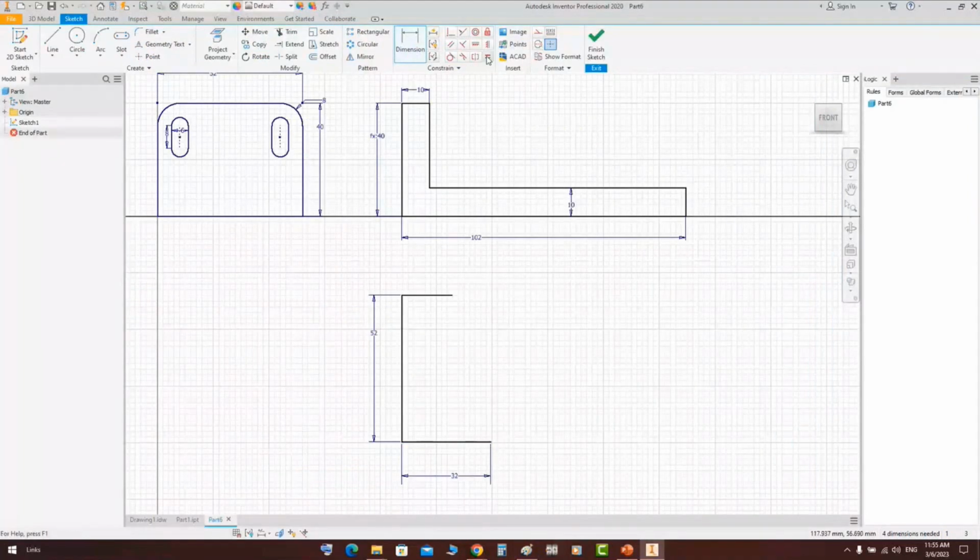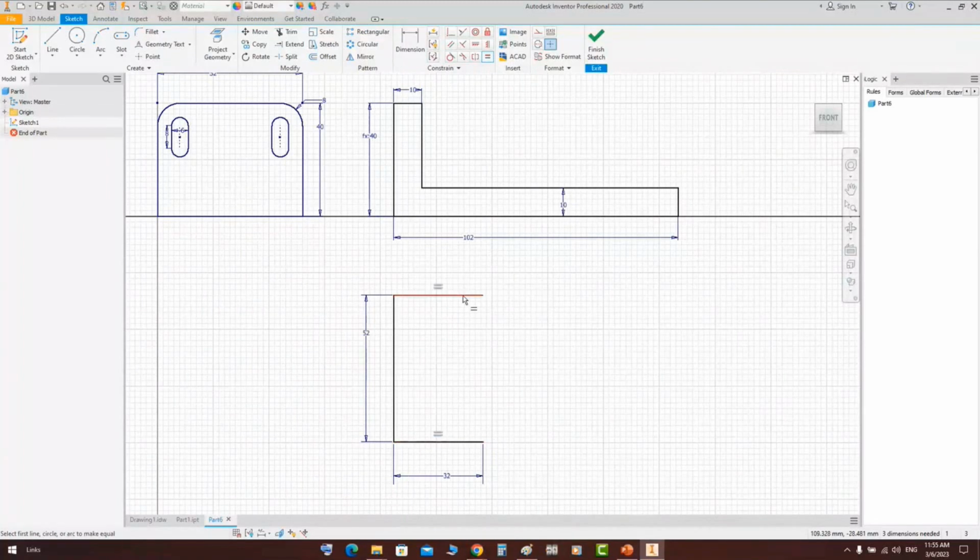And you can use equal to make those lines equal to each other. So this line value will equal that one. Okay, and if you select one of them, you can see that the equal constraint appears here and the horizontal constraint appears here. This line takes two constraints, which are horizontal and equal, and that one takes a vertical position and is perpendicular to that line.